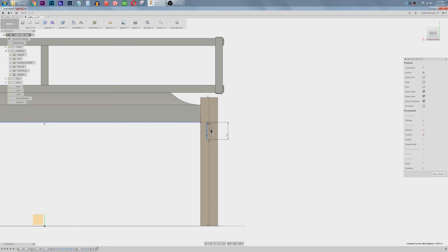All right, now my material width is 0.75 inches. You know what? I lost my center constraint. Let's just back up and punt. Let's grab all that and delete it. R for rectangle, from the center. Let's grab right here and say that. D for dimension, this is 0.75 inches. This is 1.75. And now, where do we need to go in this direction? This line and this line are collinear.